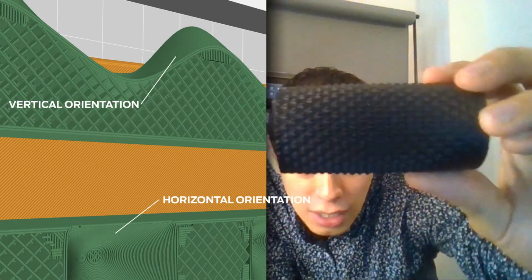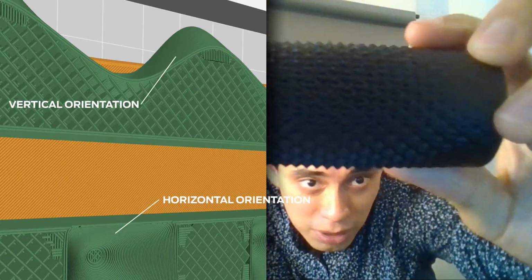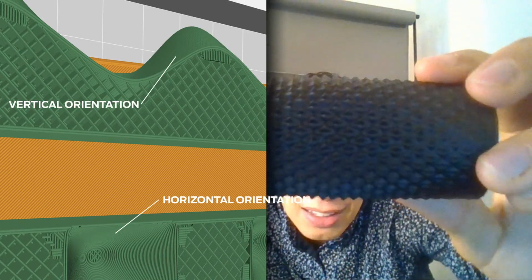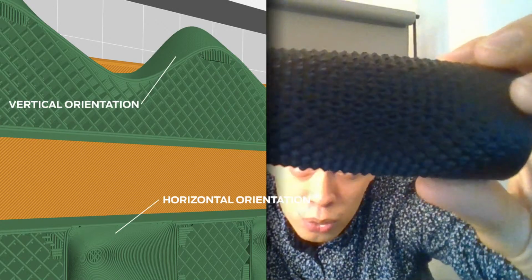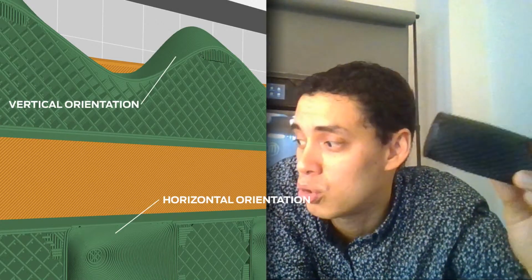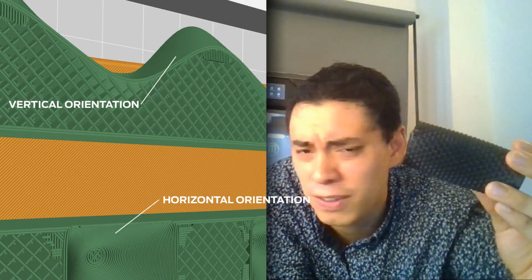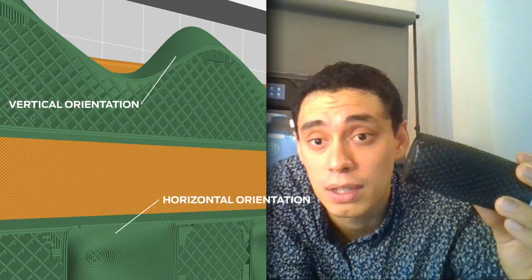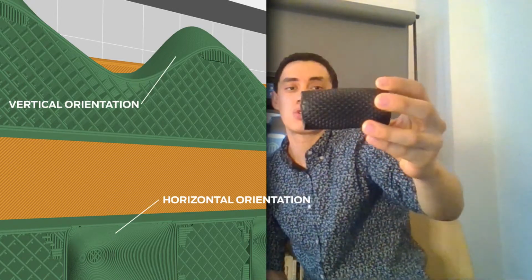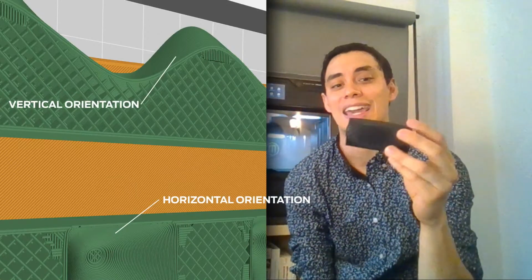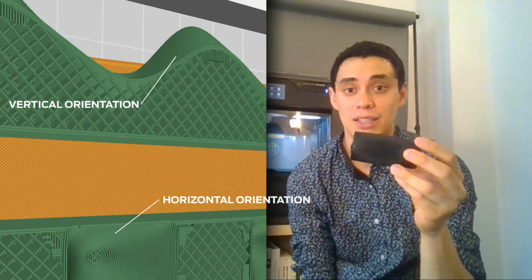These pyramids are 3 millimeters high, the highest ones, so 3 millimeters times 200, about 50 layers to finish those triangles, which is going to diminish a lot the resolution I can get when printing the part.